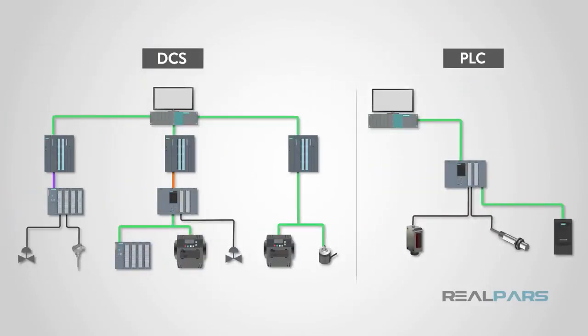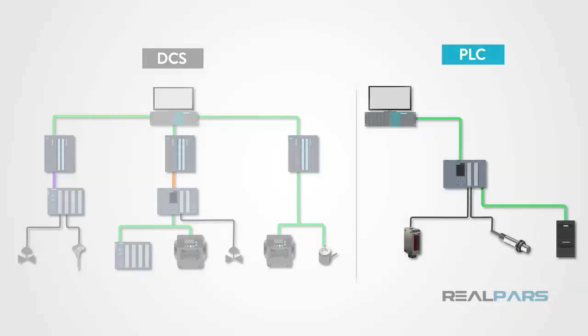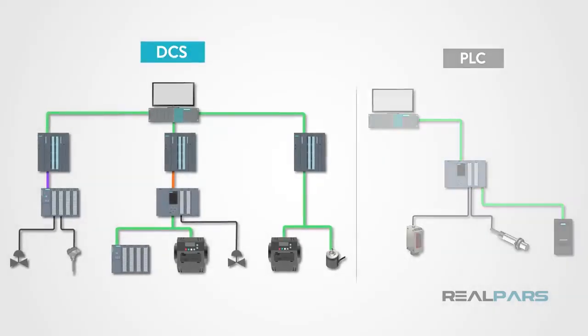In short, both PLCs and DCS have their place in the market today. PLCs would work best in a small production environment, where component failure, if no redundant system is deployed, is a small risk for the application, the budget is restricted, or the tasks and I/O count are minimal. A DCS would be better used in an environment where there are large I/O counts, with many continuous processes.